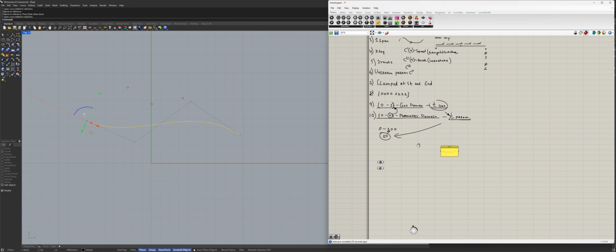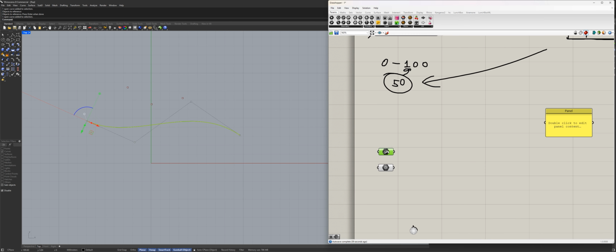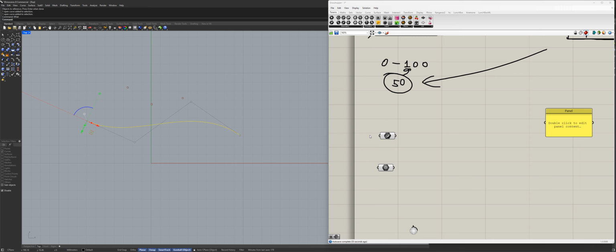So now we need to visualize this stuff and how the mapping actually works in practice. So this is the curve, right? Now this curve has a domain. We click and see that this domain goes from 0 to 180. I remind you, this is a parametric domain. Can I visualize it in Grasshopper? Well, we already know how to do it. We go to the primitives and pick the domain. Which one? These or this? Curve Domain, one number. Let's try this one, right?